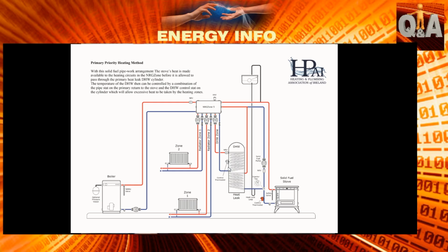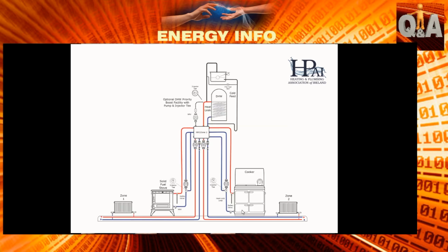With you. In that system, really, there's a couple of unique things, but if ever there's a problem with pitching, where the expansion is pushing water up over the top of the tank, you can put a half-inch feed from the expansion across onto your cold feed in some situations where the two pipes are joined close together as they attach to the neutral point, so that you don't have a movement of water through them. If the water ever builds up on the expansion, it'll fall down through that bypass pipe across and into the cold feed, and it will stop the system pitching.